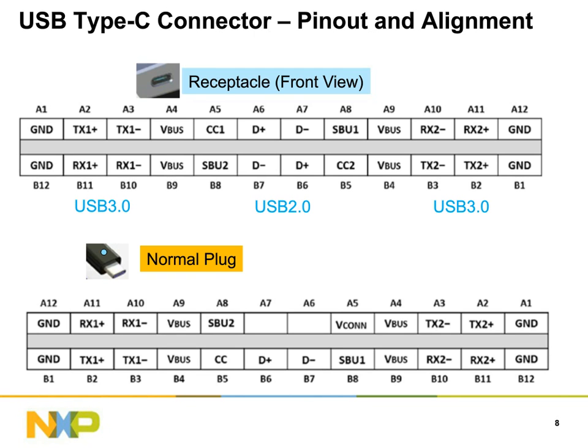You also see the VBUS pins, which is your main power line, your voltage line, where you're going to see the main voltage and current for your bidirectional communication. You also see 2 pins called CC1 and CC2. CC stands for configuration channel, and these are the pins used to exchange messaging on both sides and establish who is going to be the provider and who is going to be the consumer.